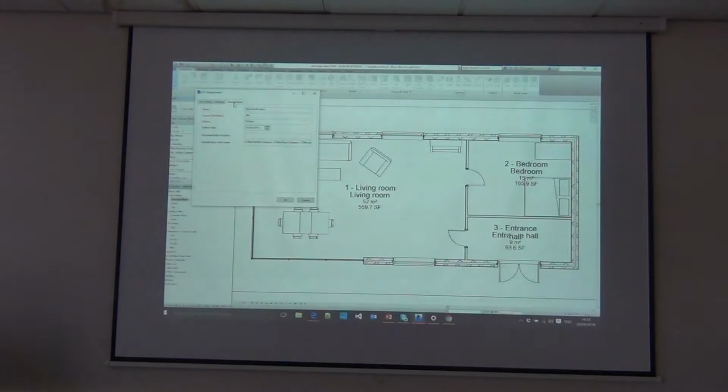And then this is the most important tab. Essentially here, Revit doesn't have the concept of classification. It has properties. It doesn't have classification. And classification is hierarchical, and it's codified, and it's meaningful. Revit just has properties that are strings or numbers. Okay. So what you have to do in order to classify these objects, to give them back to your client and to do it properly, is you have to say what classification system you're going to use.